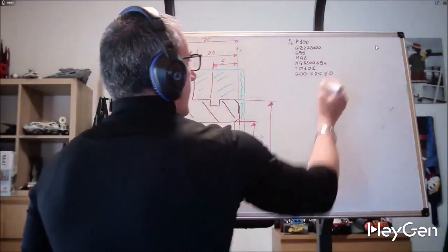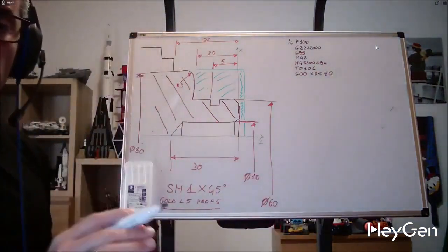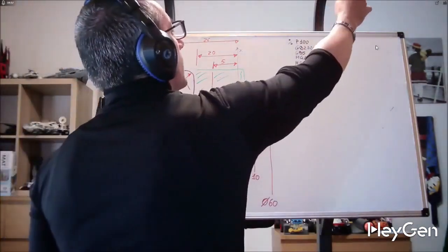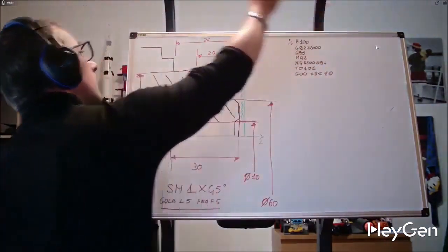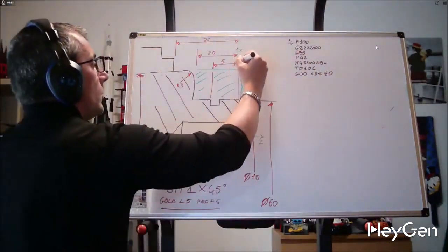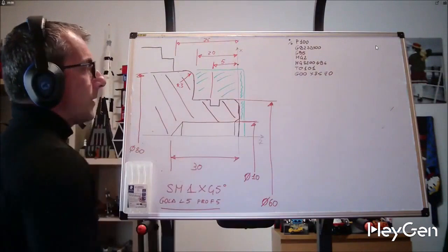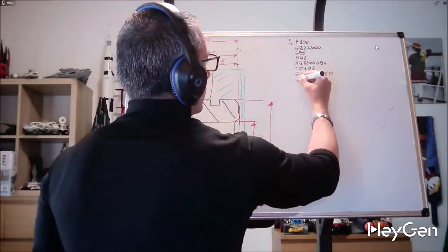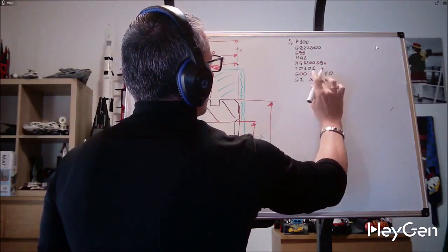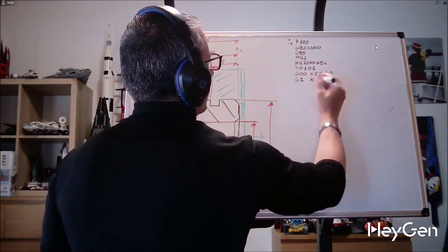Okay, very educational. If I were on a machine, what would I have done first? First, a nice X200, Z300, then first Z0 and then X85. I have brought myself here. Perfect. G1, let's do this piece. G1 X0 actually.